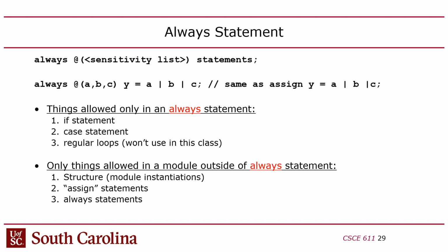I know that's confusing, and it's another one of those things that I don't like about SystemVerilog. I say that because I've been teaching it for a long time, and I know it's hard to teach because it makes no sense. Why do we have a statement that can make clocked or unclocked logic and another one that can only do unclocked? It's just weird. I don't know why they did it that way. So normally I try to stay away. I don't generally use an always statement to do combinational logic. I only use assigns for that.